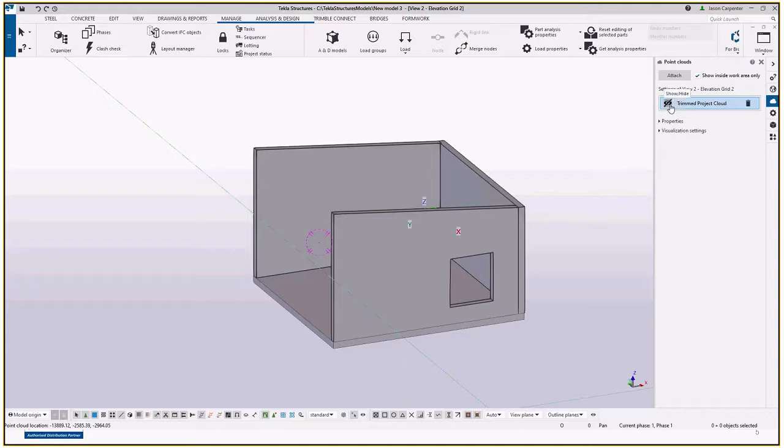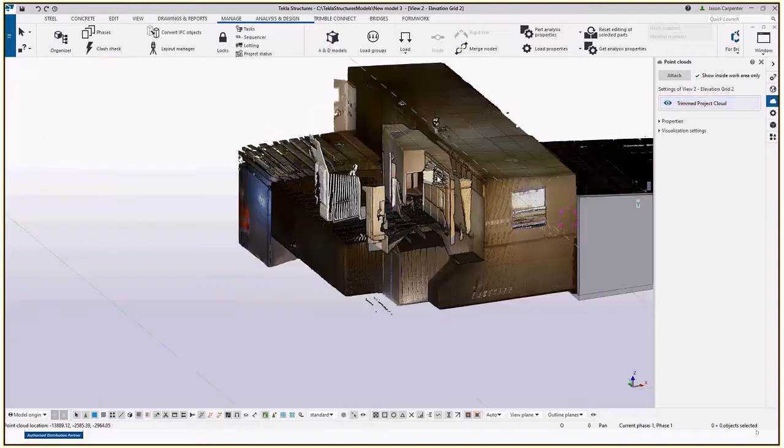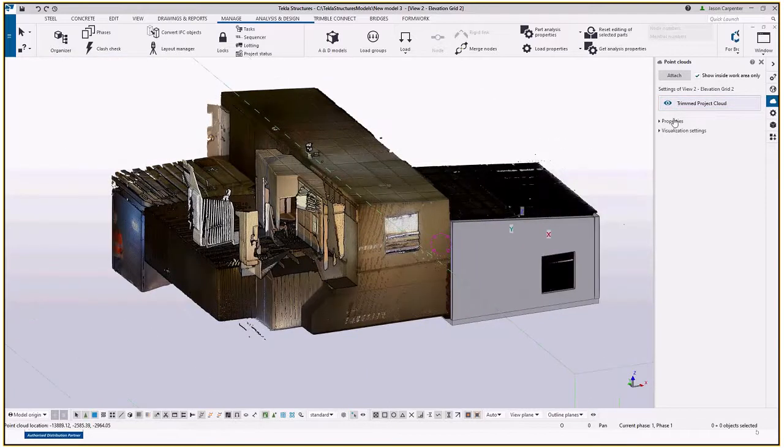Something to remember as well: basic modeling techniques such as move, select, undo, rotate, copy, and pop-up menus with the right click aren't available when you're working with point clouds. So once you've got this open, we can't move it with our mouse. We are able to move it using the positioning system, so if we've done a measured move, we can move this. But 9 times out of 10, if you're working within the project, all this should be in the right coordinate system anyway.